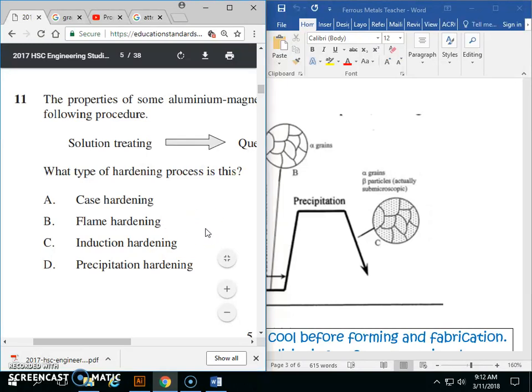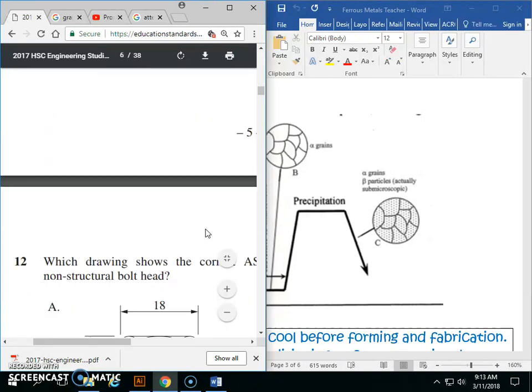There are three main classes that are heat treatable. So the 2000 series, which has copper, and the 6 and the 7. Sorry, 6 is with magnesium, so Dirty Harry, and 7 is like 7-zip, if that helps you, because 7 looks like a Z. Zinc, yeah, zinc because it looks like a Z.